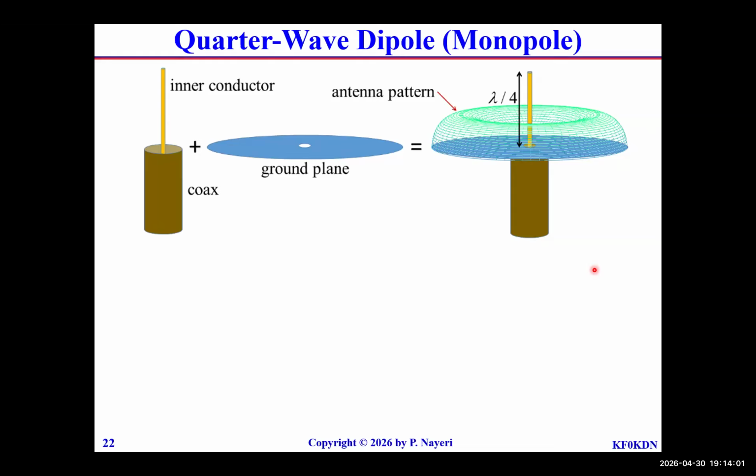The best solution is generally what we call a monopole antenna, where you would have the ground plane like this, and this, which has a length of λ/4. Similarly, you're probably going to feed it with the coax. If I recall correctly from what I discussed earlier, you folks are planning to use a BNC connector to connect it, right? So you have something like this.